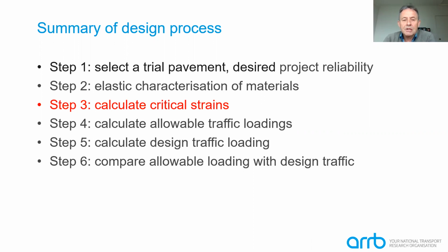And so you might start with that as the trial pavement configuration, select a thickness of working platform based on your experience and the subgrade strength on that particular road. You would also consider the design traffic loading on this road and select a trial configuration for evaluation.